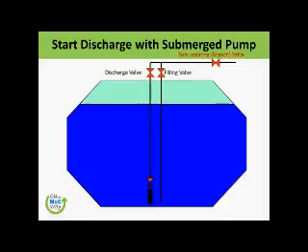Once we have got the cargo moving inside it, this one will be fully shut, this one open, this one partially open, so slowly open, say about 12%, throw the liquid here, start the pump. When we have got the liquid flowing normal, amperes on the pump are settled, the pump is not hot anymore, adjust the motor load slowly and start slowly opening the tank branch valve or isolating valve, and the cargo will start flowing outside.